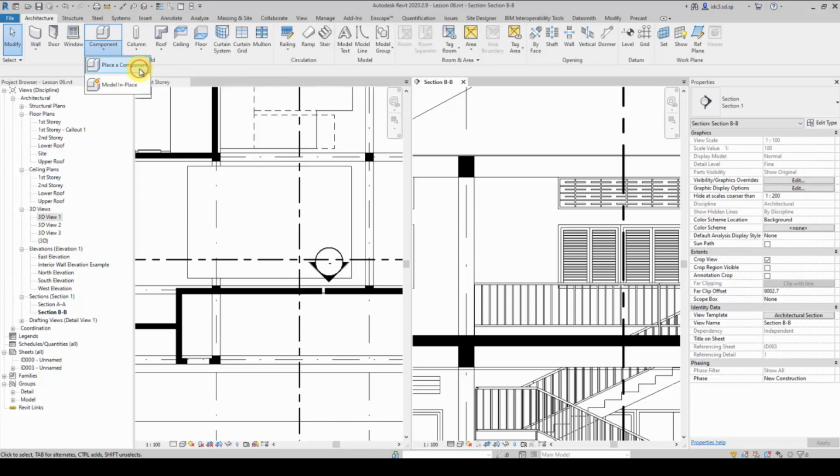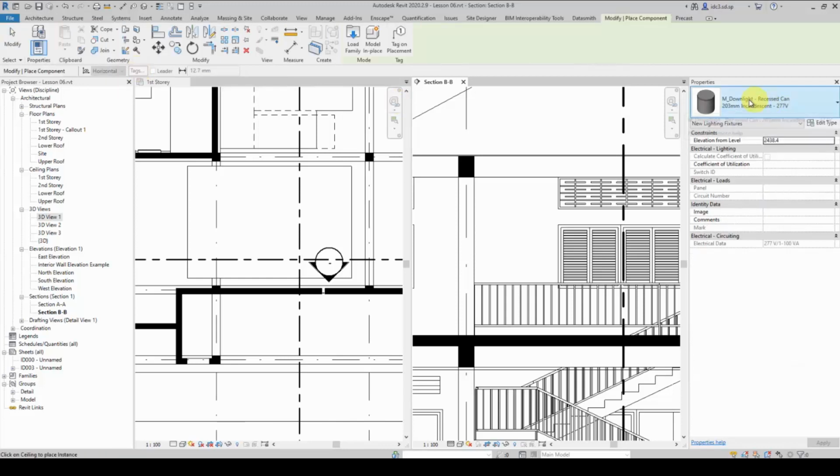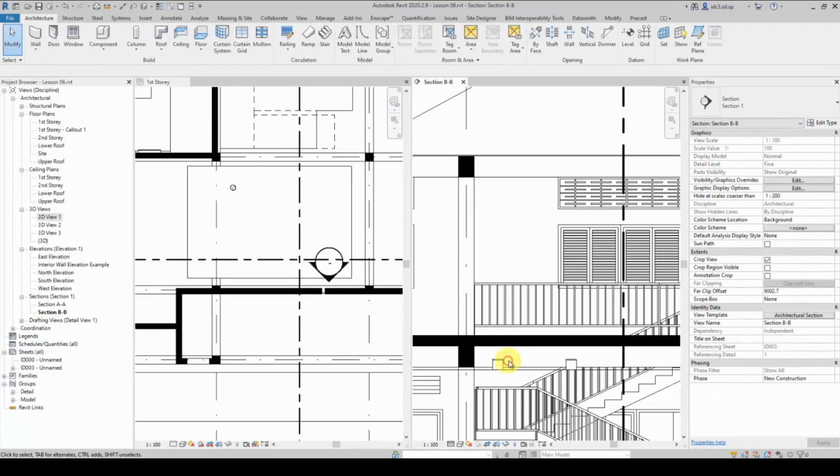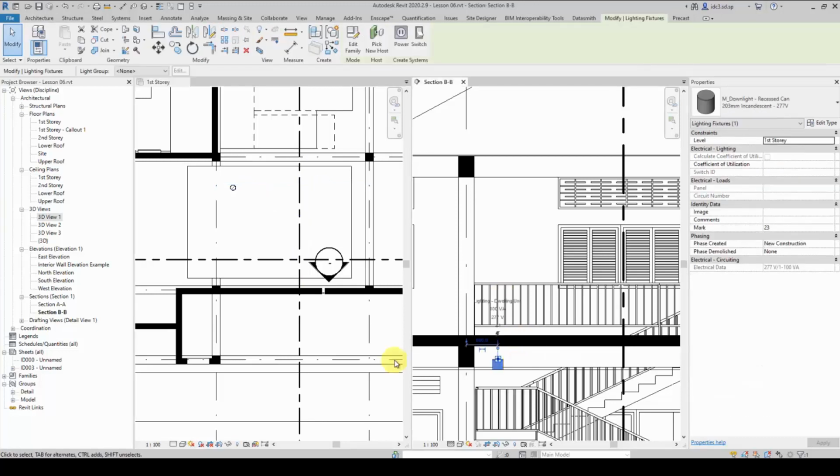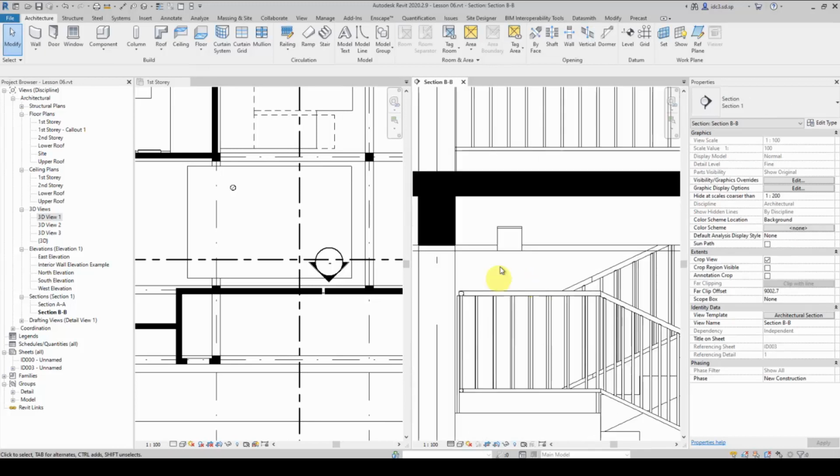Without the ceiling board, it's going to create quite a lot of havoc, in which sometimes we may not be able to manage it correctly, and then we just keep clicking and creating more and more down here. That is not a good idea, because later on you'll mess up our model. Okay, I'll show you another example like that. If I do the same with this recess can and I don't have a ceiling board somewhere, it disappears.